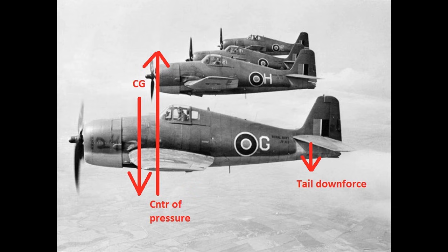First of all, notice that the wing doesn't have to support only the weight of the aircraft. It has to support the weight of the aircraft plus the tail downforce. Of course, this causes a hit to performance because the wing has to fly at a higher angle of attack for a given airspeed and G loading because it's carrying a heavier load. Drag is also increased. For the moment, let's assume the CG is fixed in flight and our Hellcat is flying along at 180 miles per hour indicated.